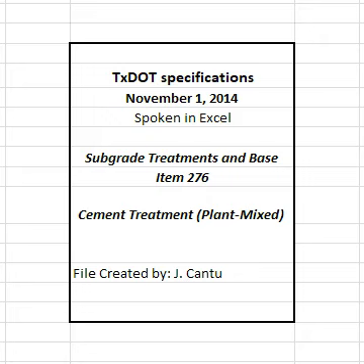Remove material that does not meet density requirements. Remove areas that lose required stability, compaction, or finish. Replace with cement-treated mixture, compact, and test in accordance with density control methods. The engineer may accept the section if no more than one of the 5 most recent density tests is below the specified density and the failing test is no more than 3 pcf below the specified density.